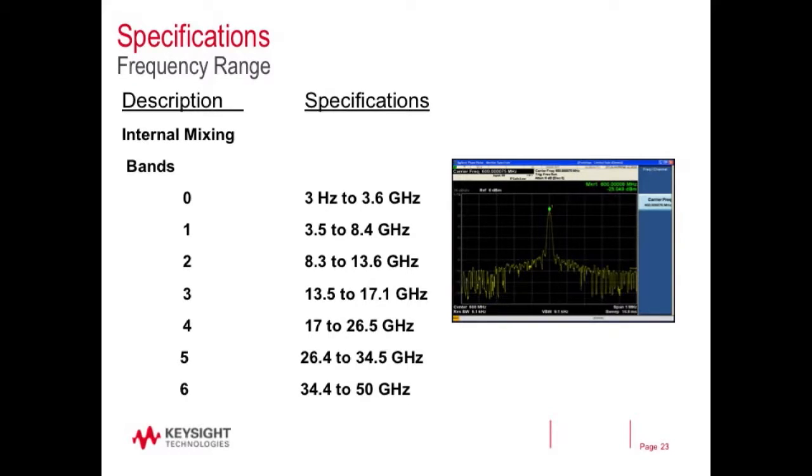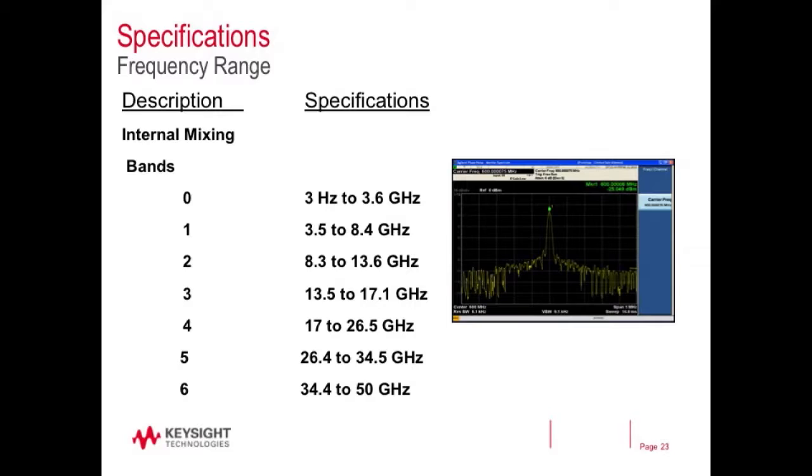It's also something useful to keep in mind. Sometimes, right, if you're doing a broadband sweep, you'll see a little change in the noise floor or something. Let's say the 8.4 gigahertz point or the 13.5 gigahertz point. Well, these represent frequency switch points. And so if you're operating at one of these switch points, it's good to know that,